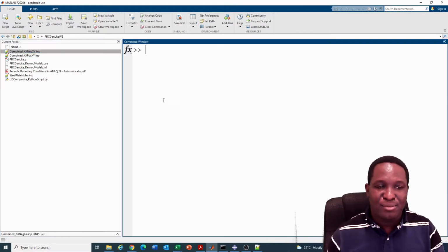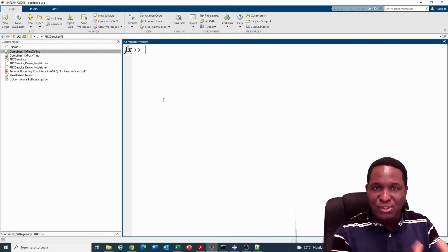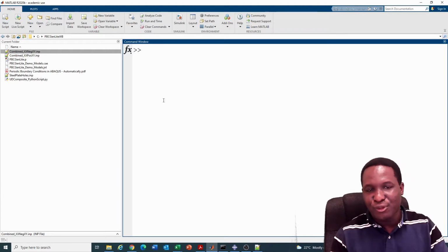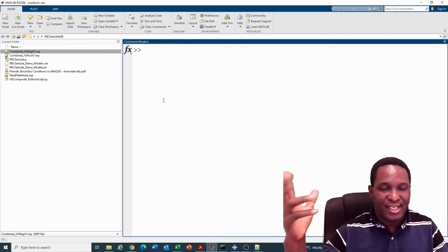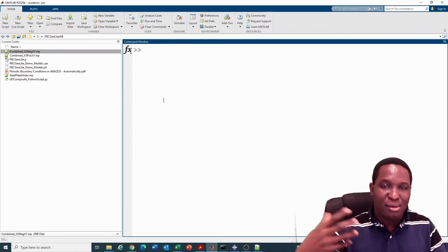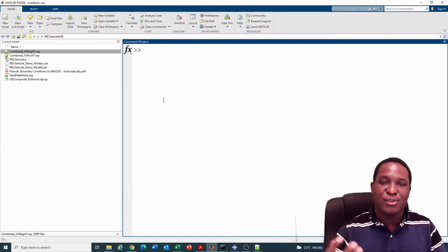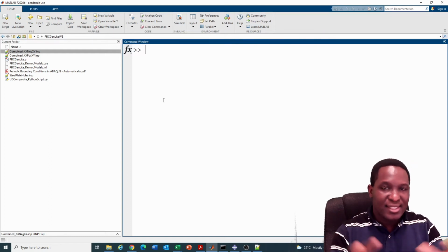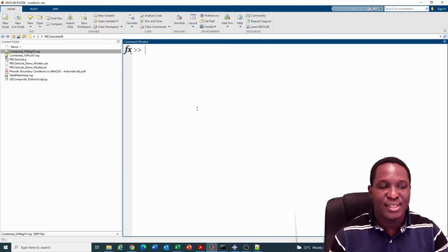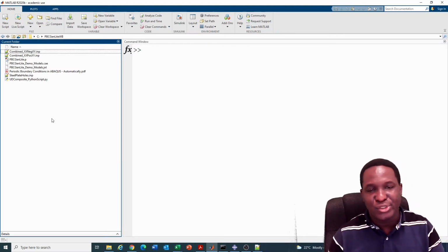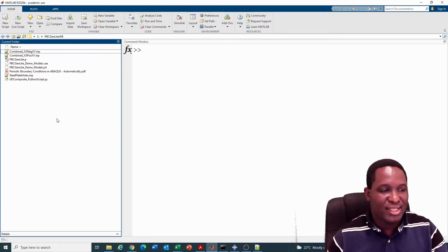Clearly, for us to be able to apply periodic boundary condition, we need to use PBCGenLite. Again, if you don't know about PBCGenLite, the video in the link that I put above in the card would explain what PBCGenLite is and how to apply periodic boundary condition on a domain. So this is what we're going to do. There are a few videos on this channel where I've used PBCGenLite to show this. So please refer to them, but we're going to show how you can do it again within this domain.